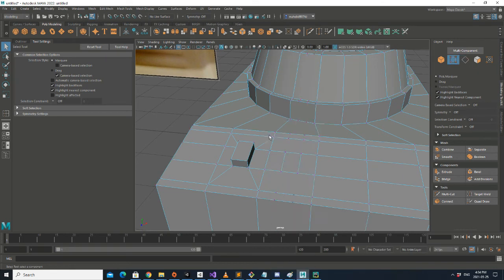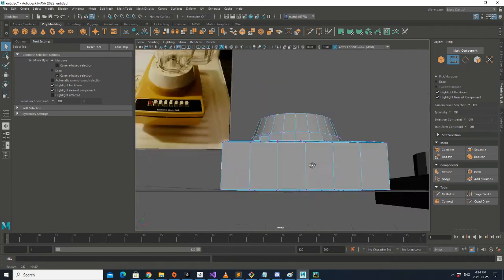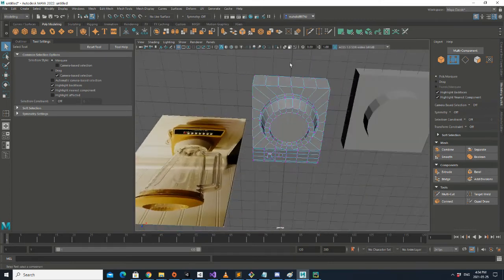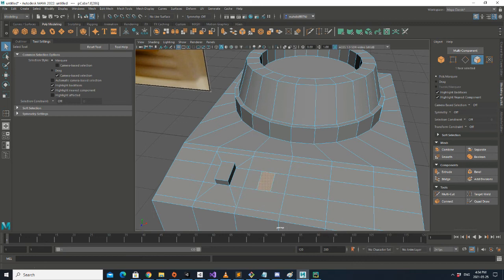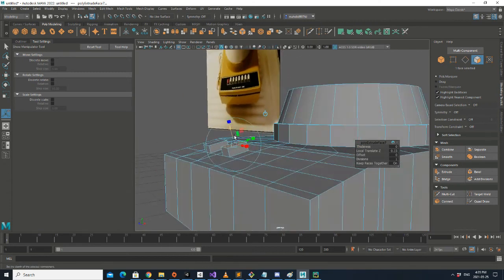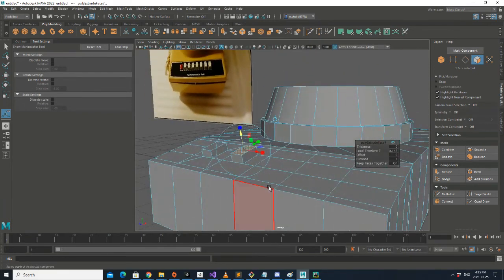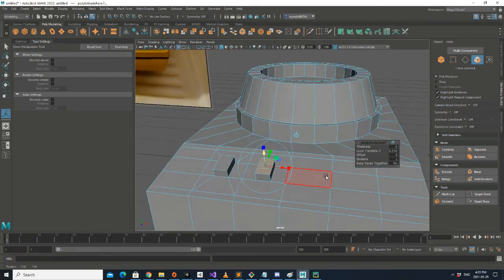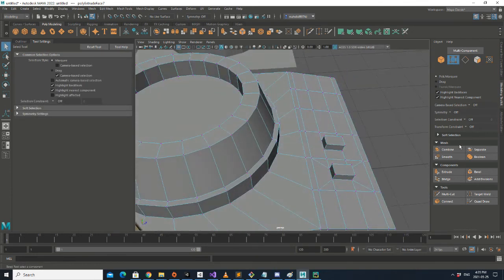And selecting all the vertices along this direction, deleting them. I think all the unwanted ones are deleted. Yeah, exactly. And now what I can do is extrude my button upward. Do the same for, let's say, having 2 more buttons here. And don't forget to do this vertex thing.